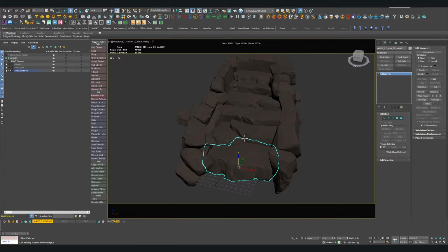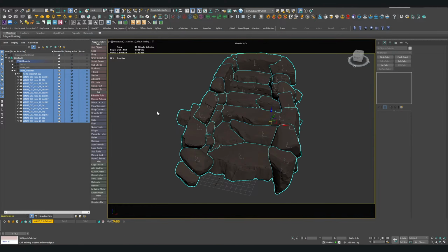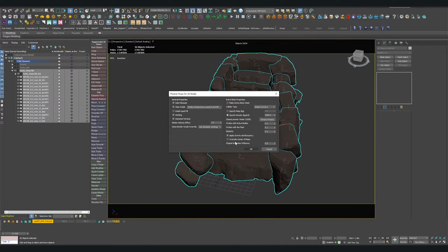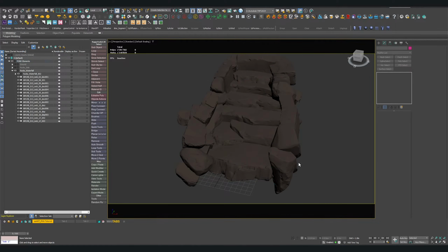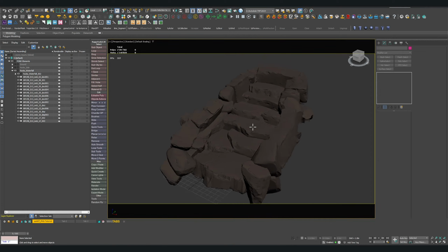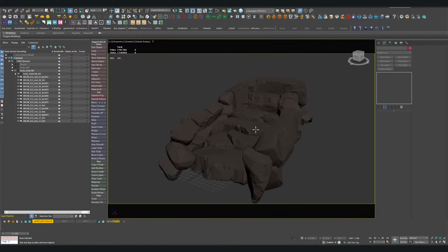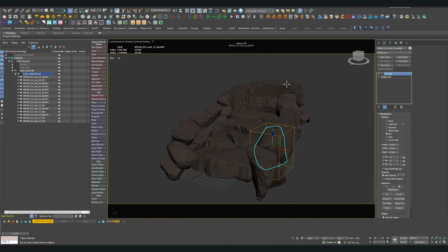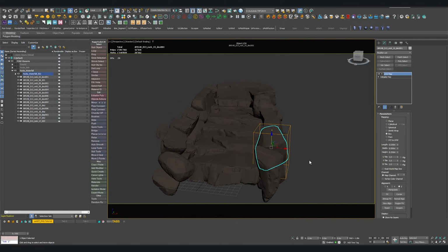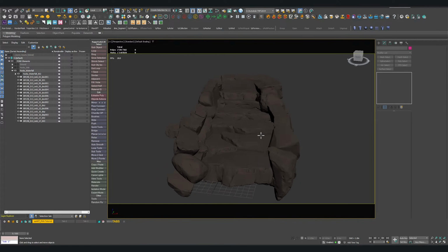And you also make sure that you select all of them and then right click, go to Chaos Phoenix properties, and make sure that the clear inside checkbox is on. That will kill every single particle that may get generated inside of any of these elements, because we don't need them inside of them.